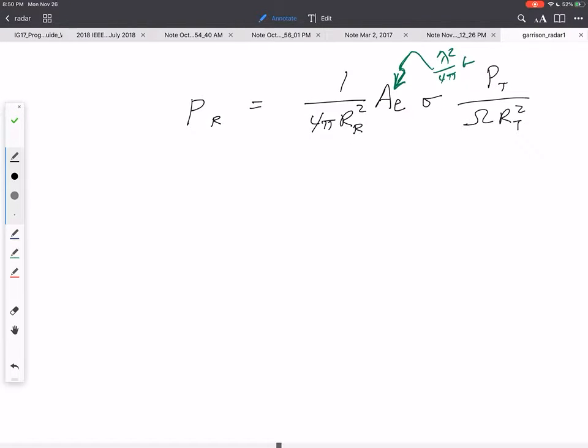So it's very similar to before, except my transmit power is now averaged over this large area. And of course I can always include a loss term. We have the same loss as before. Now for my noise, again it's the thermal noise, so I have white noise from a thermal source, and the bandwidth. This is where you have to think about the time I'm taking my measurement.